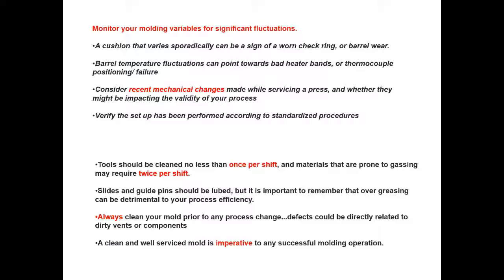Well-serviced, an example is a situation where you might end up with unplanned maintenance. If the mold hasn't been serviced and components dry up and break, well, now you've got to pull the mold, send it to the tool shop, and now you have an unplanned setup, which is definitely going to slow down your changeover time.